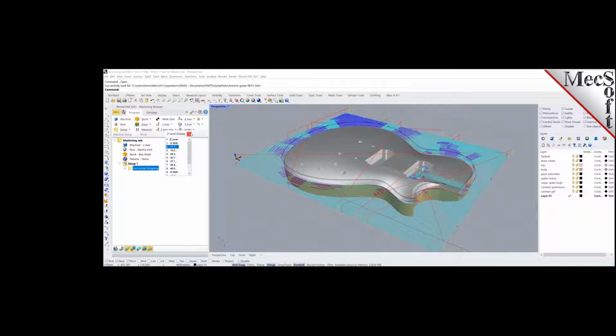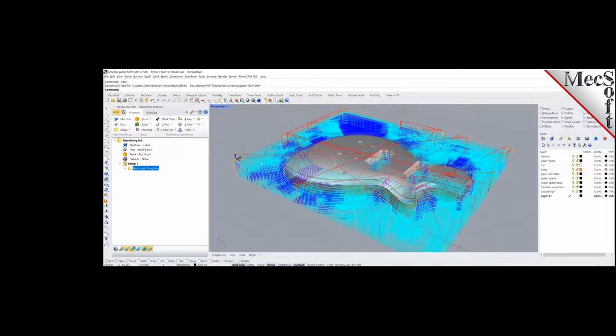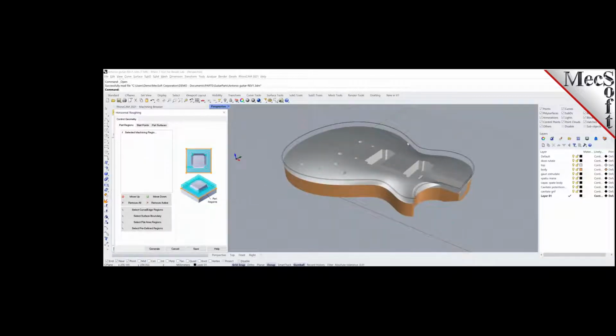One of the things you would probably not want to do is clear out all this material over here. That's silly, running your cutter and clearing the material out there. So what I would do is create a containment boundary. I can come in with a profile pass around the outside, so I just want to machine the inside portions.